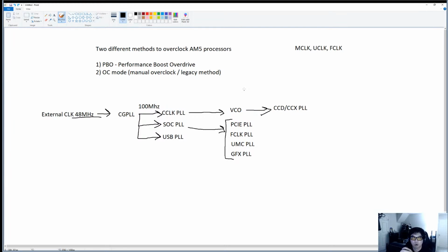From what I have personally seen, on average you're typically going to be able to do 2 DIMMs at 6,000 megahertz. What AMD has told the press is that 6,000 megahertz, or mega transfers, on DDR5 is the sweet spot, because anything above that will force you to drive the, I think it's the UMC or the U clock, at half. So that leads us to this next point here.